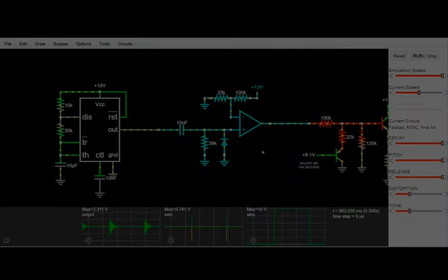This block converts long gate signals into very short trigger pulses. It consists of a high pass RC filter and an op-amp comparator. When a gate pulse enters the capacitor, a short voltage spike is generated. The comparator detects this spike and produces a narrow trigger pulse. This trigger pulse is then sent to the kick drum input. A diode is also added to block negative voltages and prevent unwanted oscillation. This stage is extremely important because it ensures that only a single clean kick is generated per pulse.